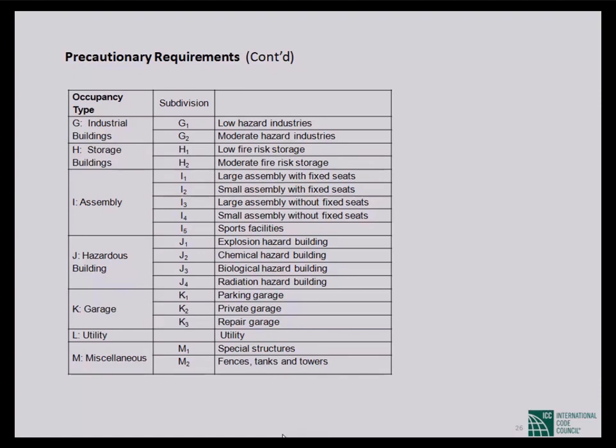So now, as per 2020, garments is classified as G only. So you cannot directly say G2, but as it is not preferred in BNBC 2020, you have to think a little bit differently. Some of the garments may be G2, some may not be. So you have to consider this one.